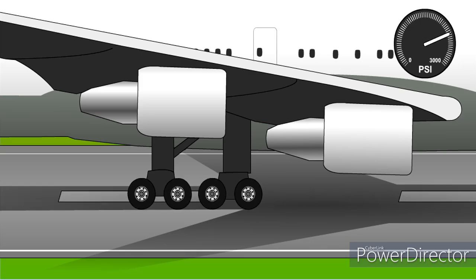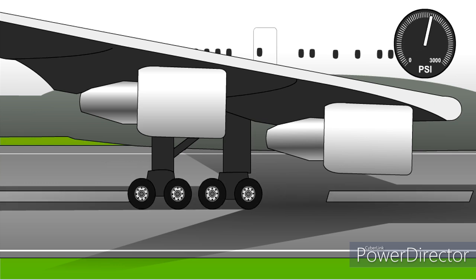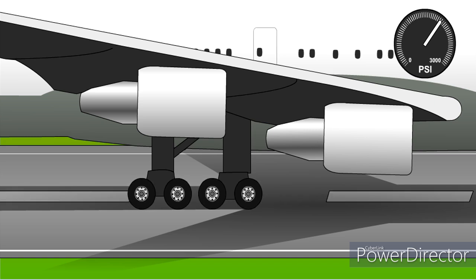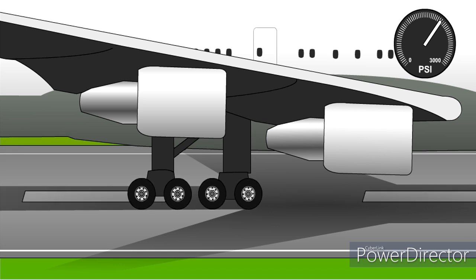Most electronic anti-skid units have an adaptive pressure bias modulation circuit. This ensures that with the pilot applying a constant pressure on the pedals, the brake pressure applied immediately after a wheel is released following a skid is lower than the pressure which caused the skid. This prevents an immediate return to the skid conditions that caused the anti-skid unit to release the pressure in the first place.